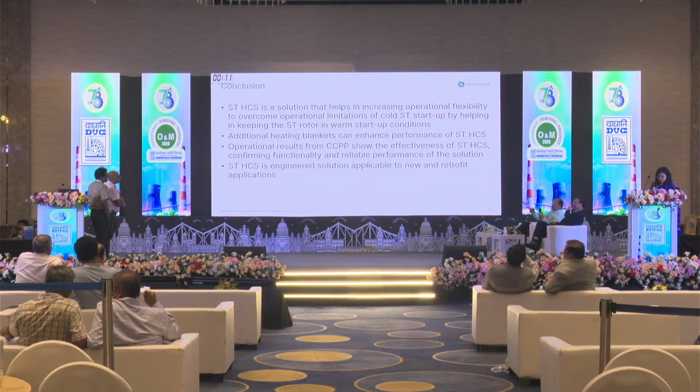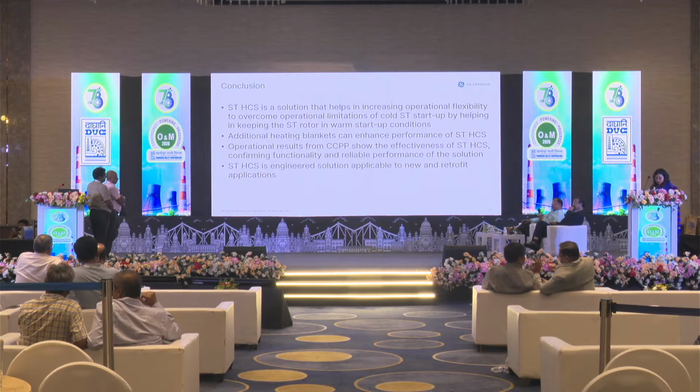How much time will it save by using this technique in cold startup? Normally, it takes around 7 to 8 hours in the unit from cold startup to synchronization. So how much time will be saved? Sir, we have seen it is saving almost 40 to 45% time as far as the turbine startup curve is concerned.